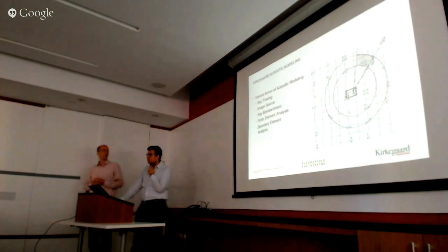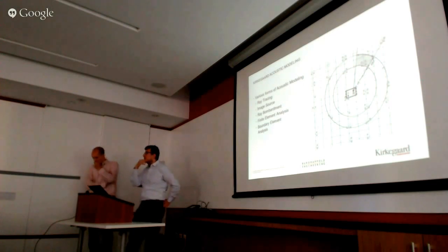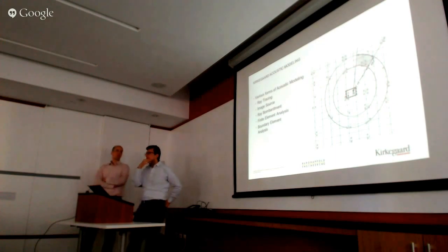Just as an analogy, in Radiance modeling, if you ever use a mirror tool, like the mirror material, you can have so many mirrors. After a while, you're not going to get any result because of the same thing. In Radiance, the mirror material just puts the sun in the total opposite direction and then just recalculates, instead of trying to rebounce the image source. It does the same thing for this.